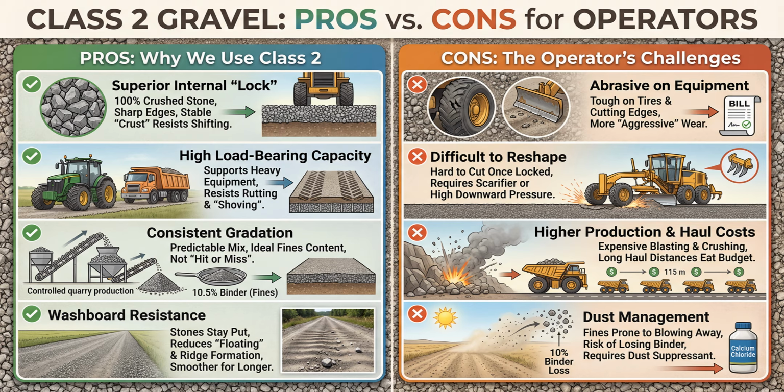Dust management. Because the fines are often crushed limestone or granite, they can be very light and prone to blowing away in dry weather. Without a dust suppressant, like calcium chloride, you can lose that critical 10% binder to the wind quite fast.